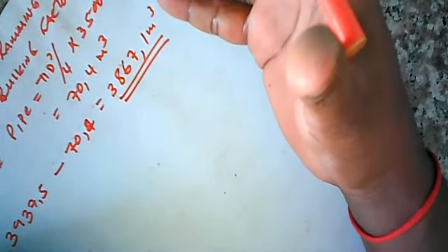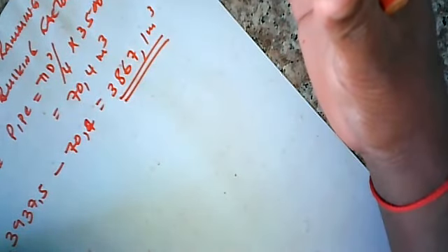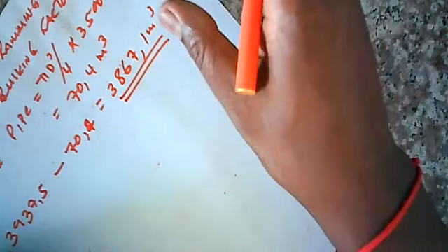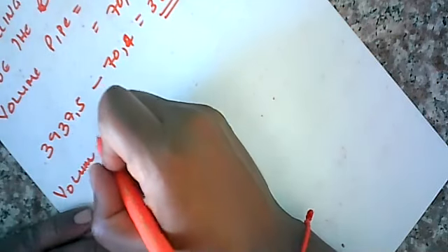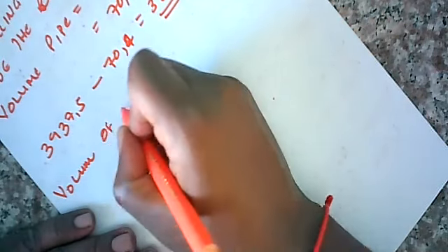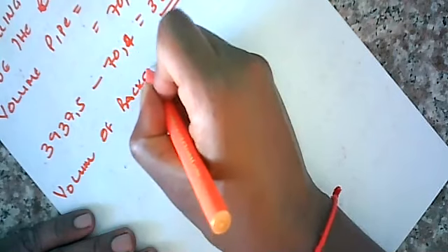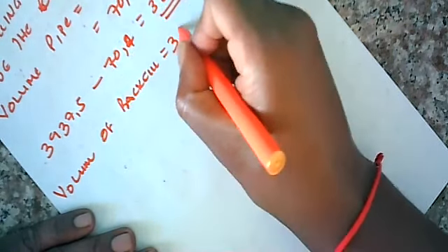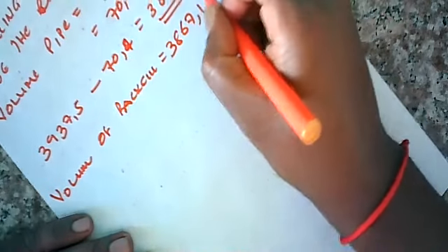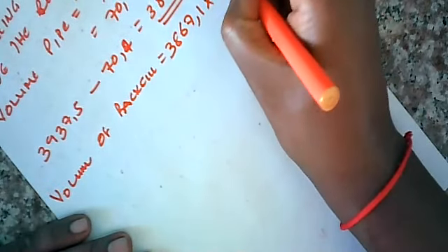All right, but that's going to go up. Why? Because you disturbed the soil. You increased the voids, or you introduced voids by 25%. So the volume we're now dealing with is backfill, 3867.1 times 1.25.